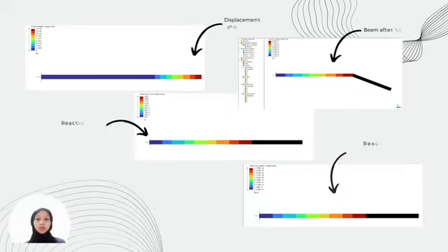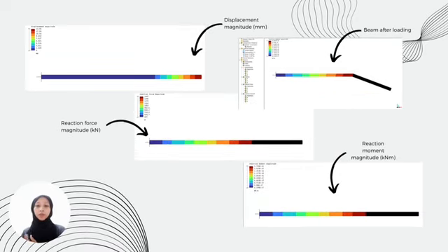In the pictures given, you can see that there are different colors of the beam, where the blue color indicates the lower value and the black color means that is where the critical points and also the maximum value are located. So from here I want to conclude that node number 3 retrieves the highest value in terms of shear, moment and displacement, and is the location where the risk of failure is located because it has to handle its own load and also the overhanging load.